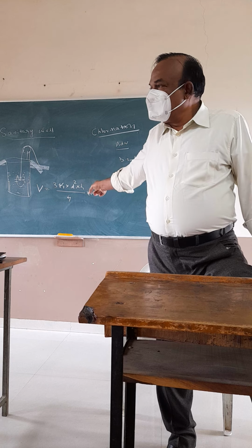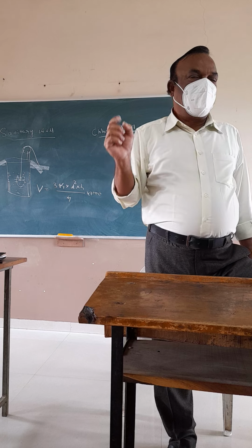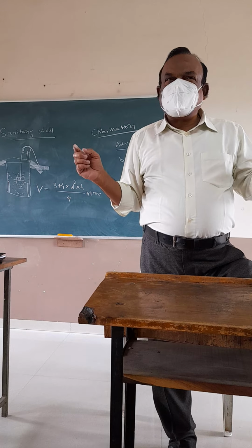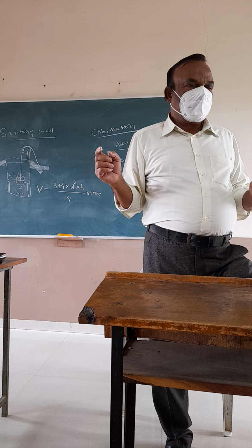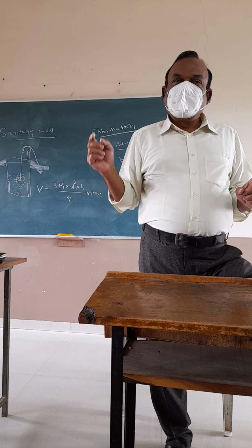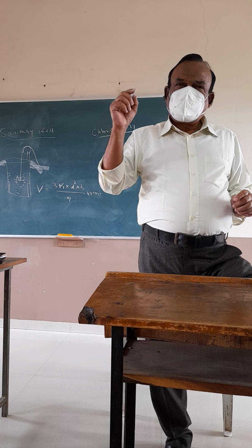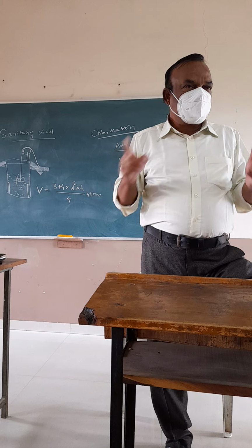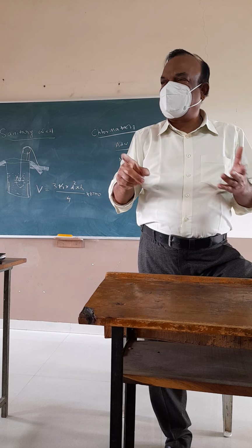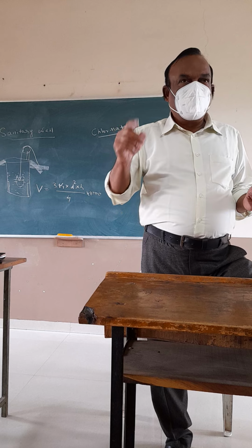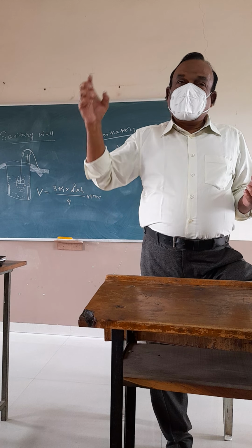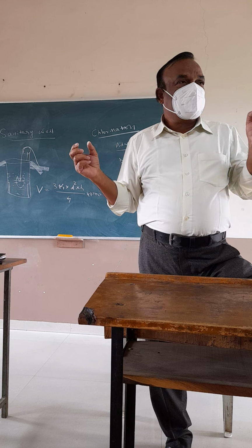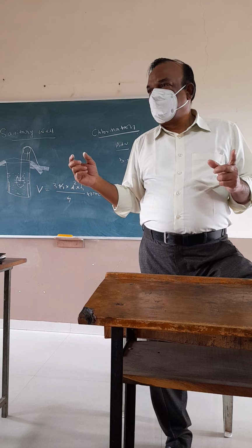is done by chlorination, and bleaching powder is used. Why bleaching powder? Because, as I told you in the last lecture, it releases the free chlorine ion, which has got the disinfective action on the water. This chlorine removes bacteria, fungi, protozoa, virus and helminth, ova, cyst. In higher or stronger concentration of this chlorine, even it kills the viruses.